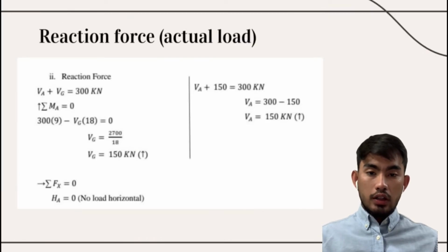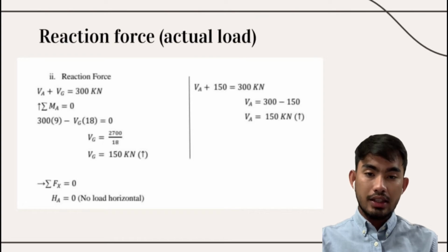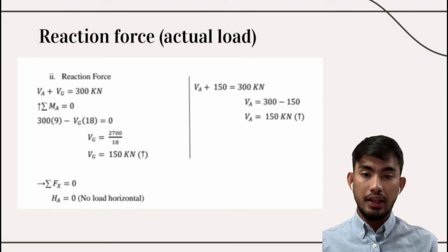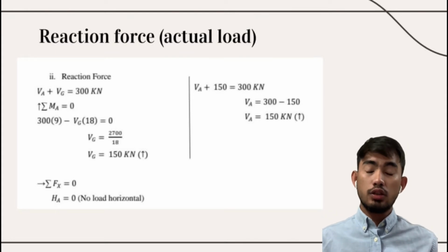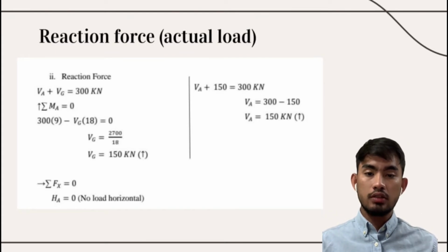After we found out that our bridge is statically determinate, the next step is to calculate the reactions for the two supports, VG and VA.